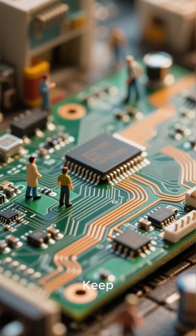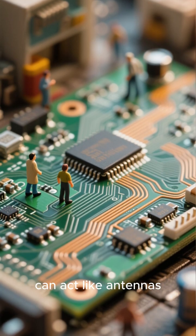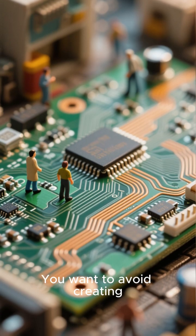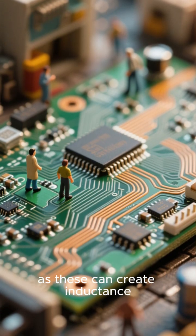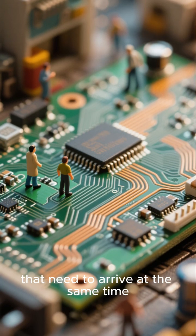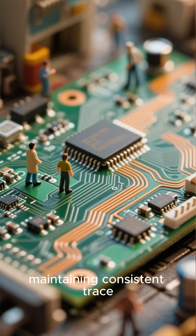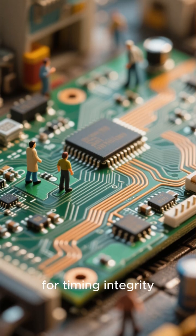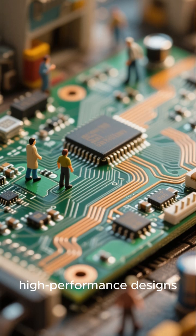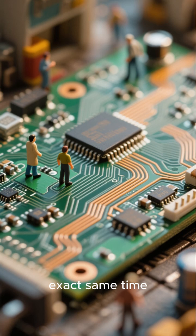The golden rule? Keep traces as short and direct as possible. Long, meandering traces can act like antennas, picking up noise and causing signal delays. You want to avoid creating unnecessary loops in your traces, as these can create inductance, which is another source of noise. For high-speed signals that need to arrive at the same time, like in a USB or HDMI interface, maintaining consistent trace lengths is crucial for timing integrity. We call this length matching, and it's a non-negotiable for high-performance designs. We're essentially making sure the signals win the race by finishing at the exact same time.